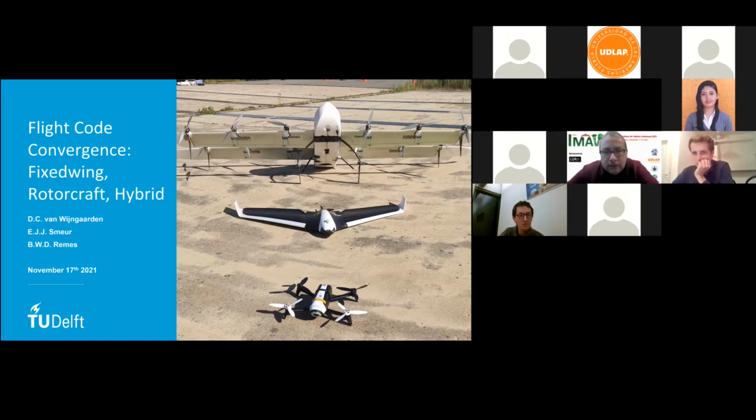Oh, go ahead. So you use the same dynamic model for all these aircraft? You just change the input matrix? That's the approach that you follow? Basically, it is, yeah. We have just a normal equation of motion for a rigid body, and the controller actually neglects the influence of the states on the linear acceleration and the angular acceleration.